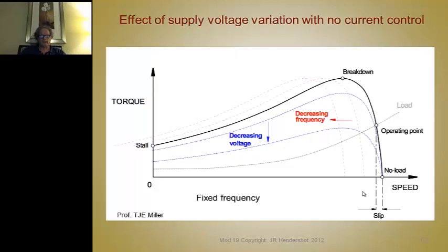So that's how the equivalent circuit parameters are measured, and there's lots of textbooks and other procedures to make those that most inverter guys are familiar with. Now let's just look at the torque speed curve for a moment and see what happens when you adjust the voltage. What happens to the torque speed curve?